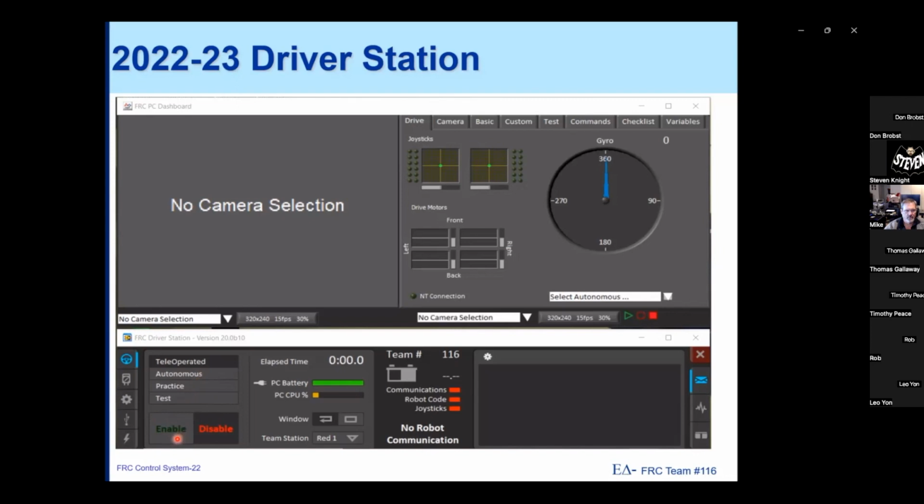Clicking enable could potentially have the robot suddenly wake up and start doing things. We wouldn't want anybody's hand to get caught in that, so we would absolutely want to let everybody know that the robot's being enabled. When you enable the robot, by the way, if you have the robot signal light hooked up, as you should according to the rules, that robot signal light will start blinking. That is the dead giveaway that the robot is active and people should stay away from it.